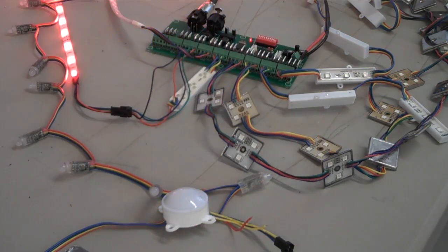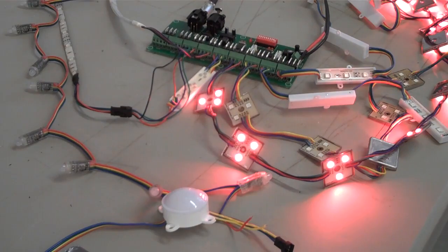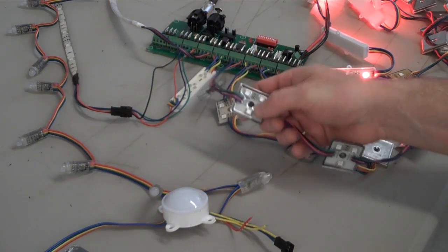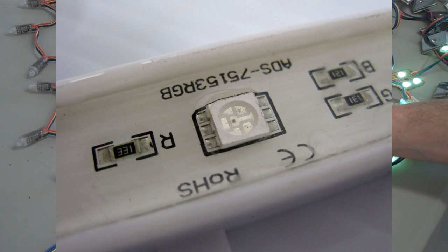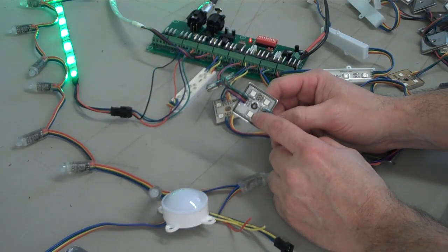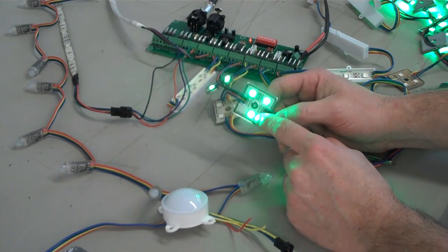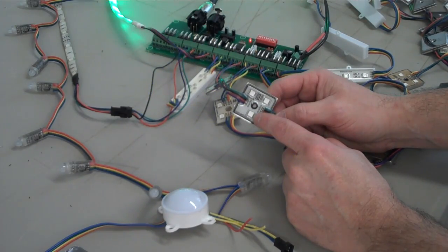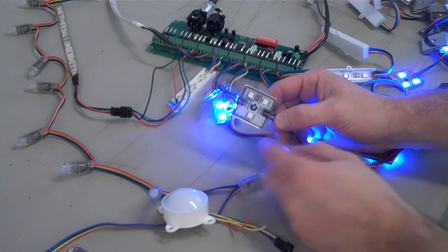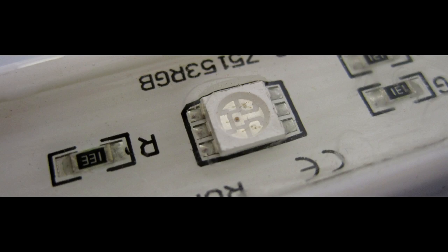Nearly all RGB devices are comprised of three different types of LEDs. LEDs are light-emitting diodes. The most common of these LEDs is one that most people are probably not familiar with. This is the 50-50. 50-50 stands for 5 millimeters by 5 millimeters. Within this small little chip are three individual LEDs, one containing red, blue, and green. Those are then mounted into a larger device, which in this particular case contains three 50-50 LEDs.